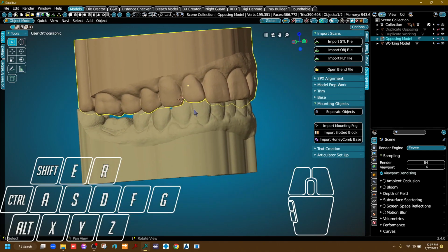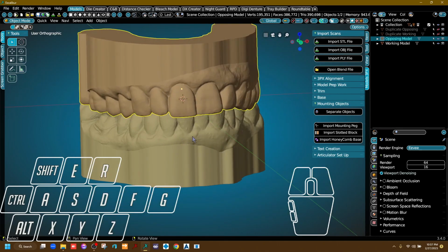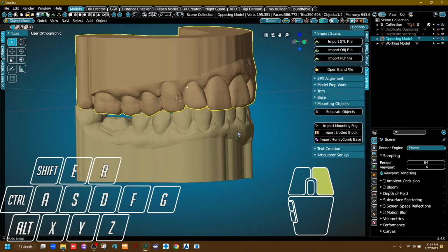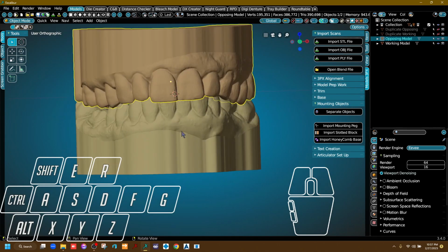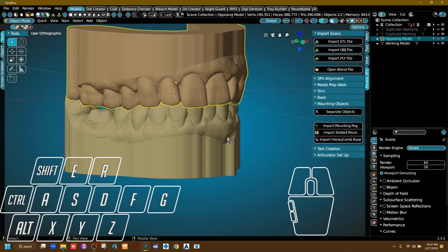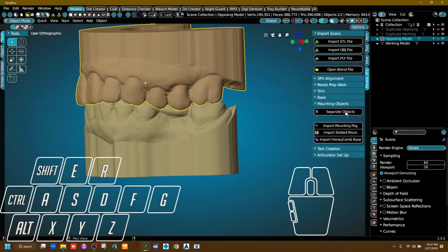So now we have two solid models here. If that's all you needed, you can print these as is. So we could export these as STL files and take them over to a printer and print them. That's perfectly fine. But if you want a little more data, in our case, we're going to want to make a section die and we want to have the names on this and everything, then that's what we're going to do next. So next thing is adding text.